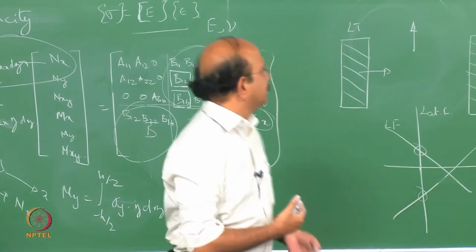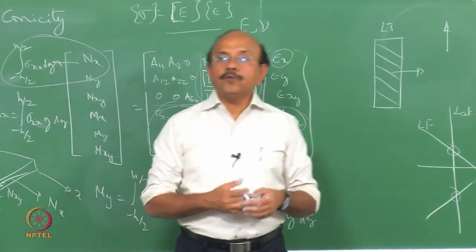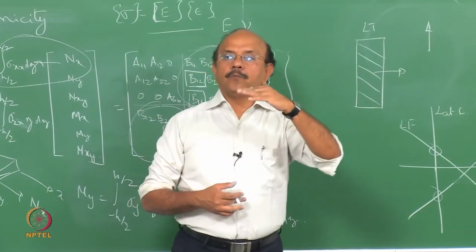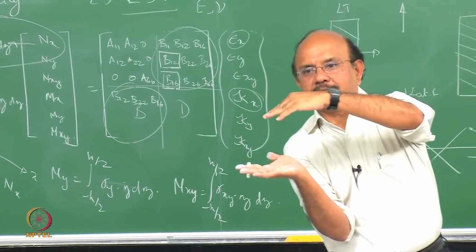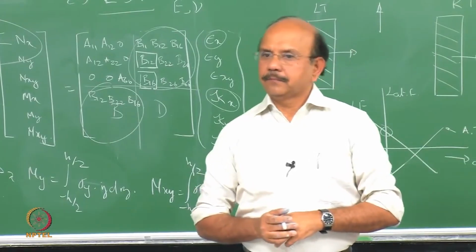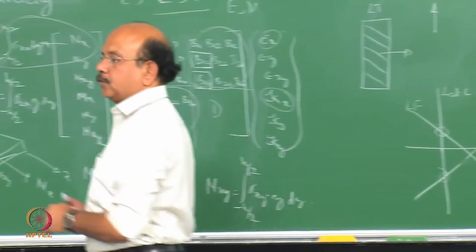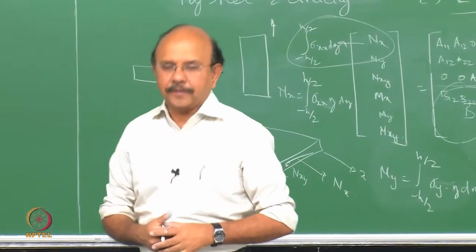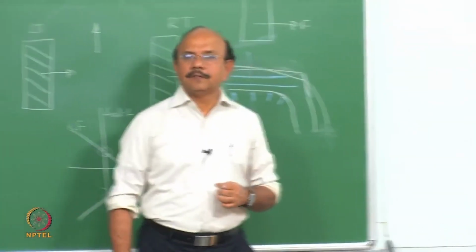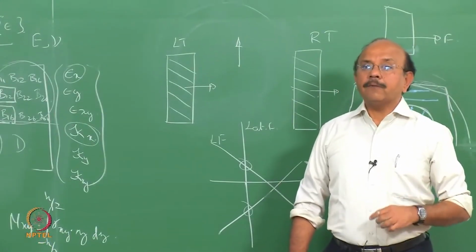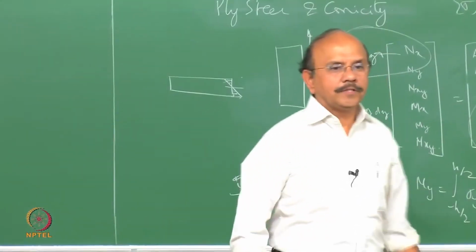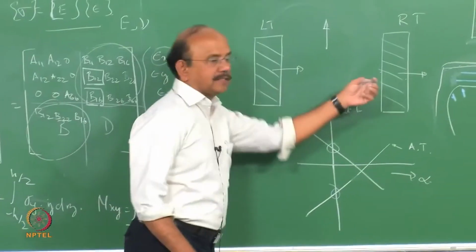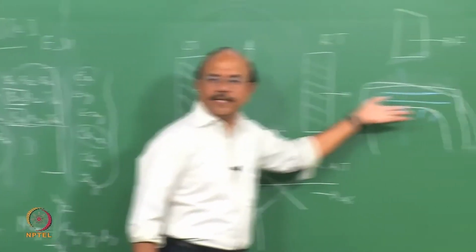So the cone, you are placing it on the ground, which means that, please note, one side of the cone is sitting like this. So this is what is called the conicity effect. That's giving rise to a force. Now, this is one thing which is not necessarily one side or the other side, because it depends upon which side it is shifted.